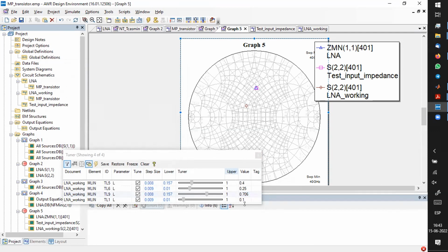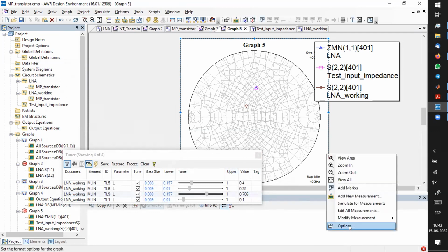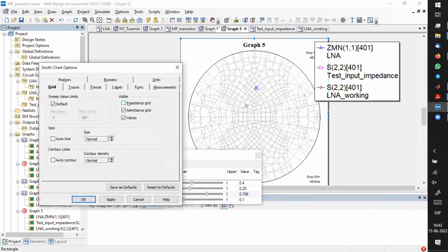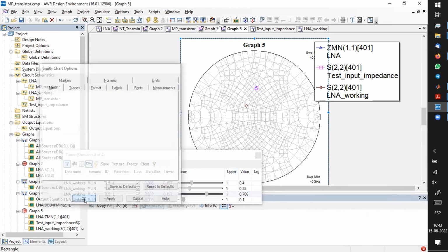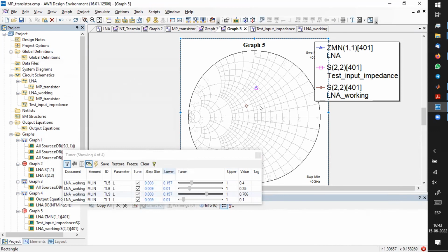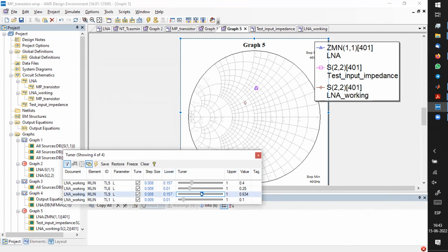It doesn't follow the admittance circle because a series line has both capacitance and inductance. It's actually following the figures that we have, but you have a really short bit of series inductance and then a capacitance towards ground. So it will follow but it will make a circle at the end.